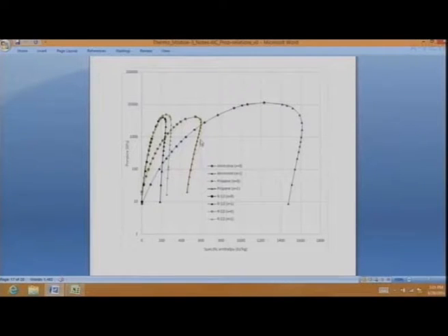So what we are seeing here is they all have the same shape, but in making this drawing, we have to be very, very careful, because in all these cases, specific enthalpy, which is here set to 0, is decided quite generally as per the wishes of the person making the property tables. In these materials, the specific enthalpy HF at 200 Kelvin has been set to 0. And so we could make all these property plots of different substances on this.